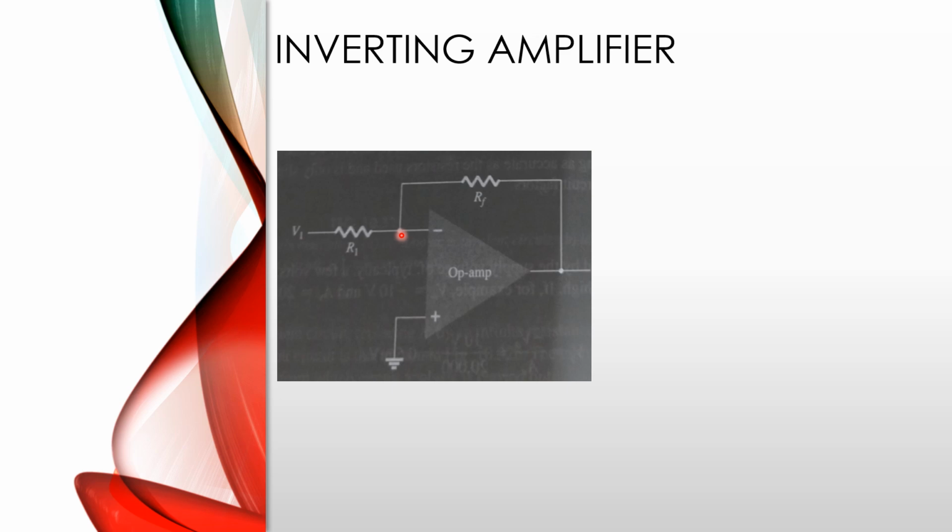We know the voltage gain means output voltage by input voltage. The ratio of output voltage by input voltage is called the voltage gain. And from the characteristics of the op-amp, we know that the gain is infinite for op-amp. If the gain is infinite, then the input voltage is 0. Thus the input terminal cannot be directly connected to the ground, but it's virtually connected to the ground. That's why we can say that this G point is said to be grounded. Okay, we can consider it.